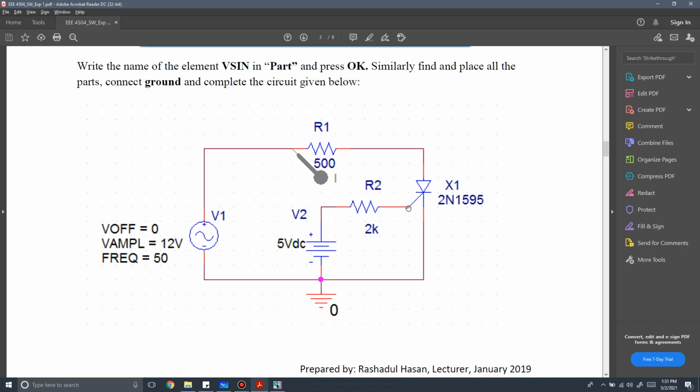The DC voltage source is connected to the gate terminal through a resistor. We need a DC source for our SCR because we have to supply positive gate current. That is a requirement of the SCR. That is why we're using a DC voltage source. And we also have our ground. So let us build the circuit first.